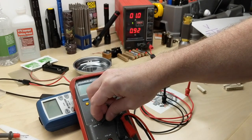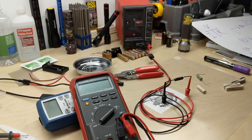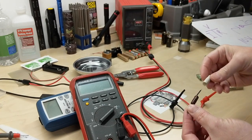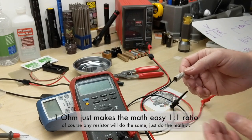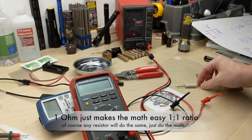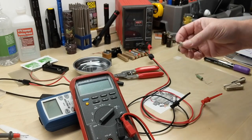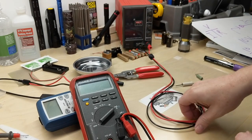And it can really come in handy when we're looking at oscilloscopes. I actually do not have any type of current probe for my oscilloscope, but with this little 1 ohm resistor, I really don't need one. If I'm interested in a circuit and want to know the current, as long as I have this 1 ohm resistor in line and it doesn't affect the load of the circuit I'm dealing with, I can check across it and plot my current as a voltage and just chart it over time, just like I can my voltage signal.